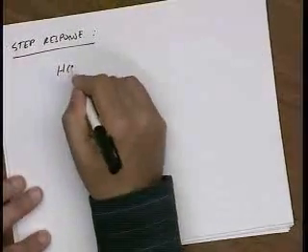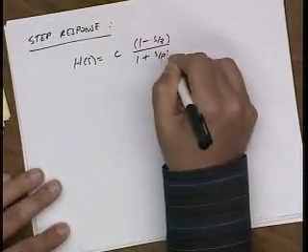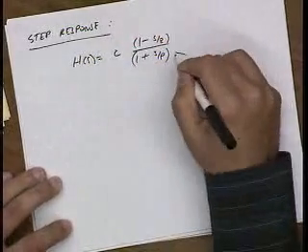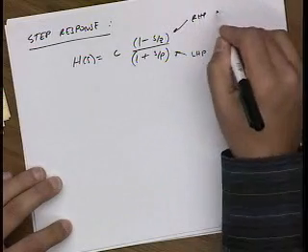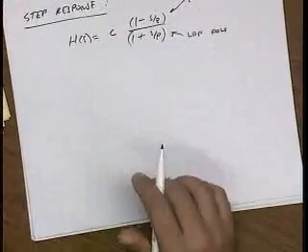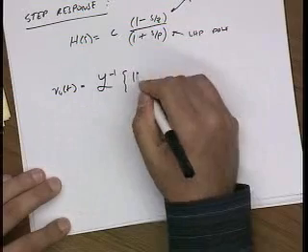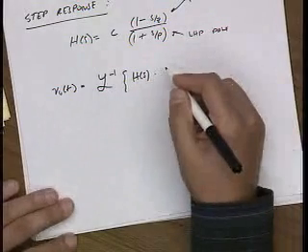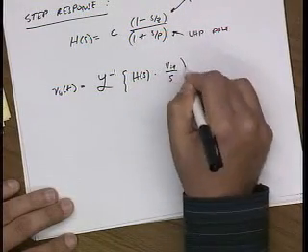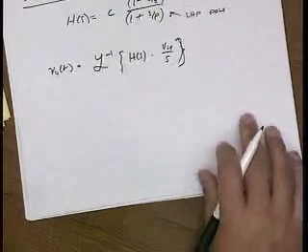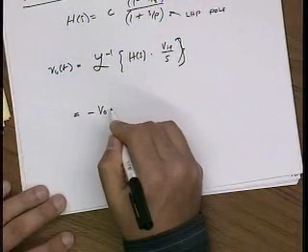So my transfer function is C (1 minus S over Z) over (1 plus S over P). So I have a left half plane pole and a right half plane zero. And the output voltage, of course, is just the inverse transform of H of S times the input, which is a step function. Let's say it's Vin over S, 1 over S because it's a step function. And you guys all know how to do this calculation.